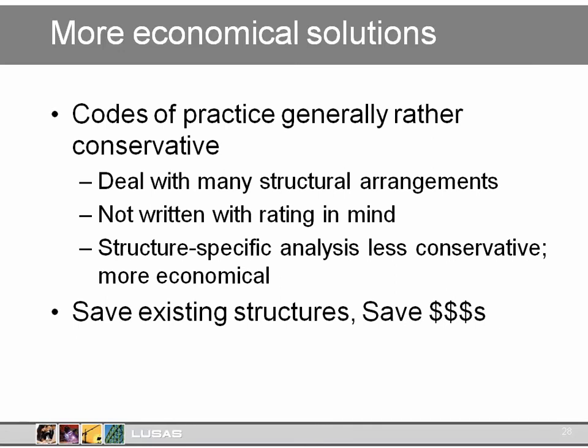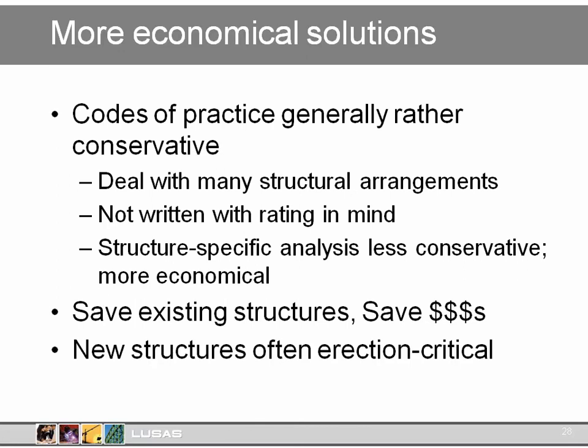In the case of existing structures, a less conservative but safe analysis can mean the difference between a multi-million-dollar retrofit or replacement or no construction work at all, so it can save big money. In the case of new structures, the buckling is often critical during erection. This infers that a more economical design probably has no adverse effect on the structure in service. It will be no less durable, no more at risk.